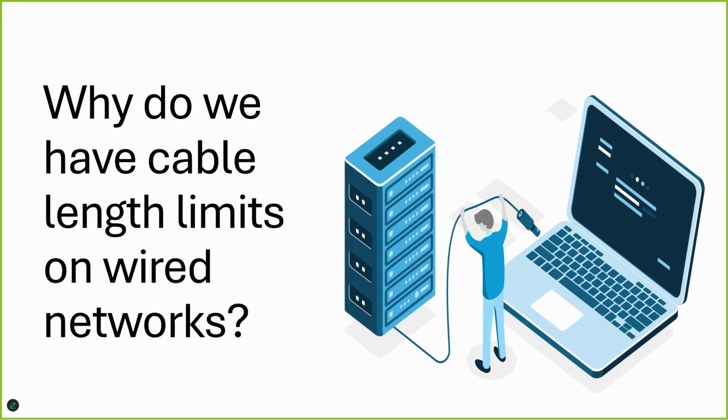So it's important to know that these things are there for a reason, and they're born out of the fundamentals. So the concept of the fact that I can't have a PoE cable, or for that matter, a data cable, longer than a certain length and still achieve a particular data rate or a particular power level, that is born out of a fundamental that signals attenuate, that energy attenuates as it travels down a wire. And so therefore, I have those higher level rules that I think about for PoE, for data communications, and so on.